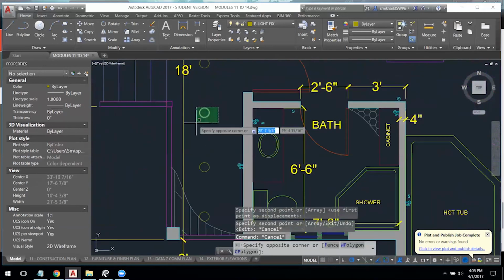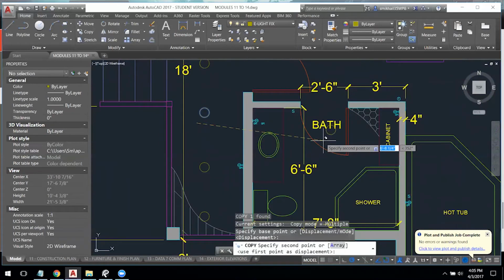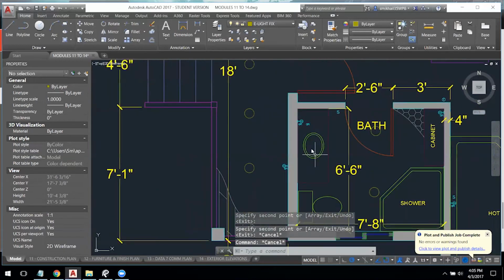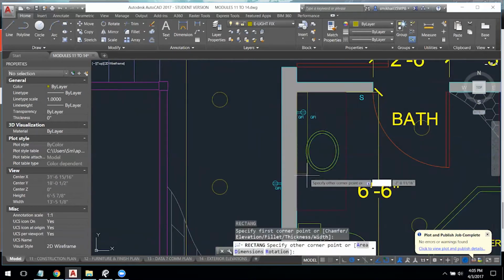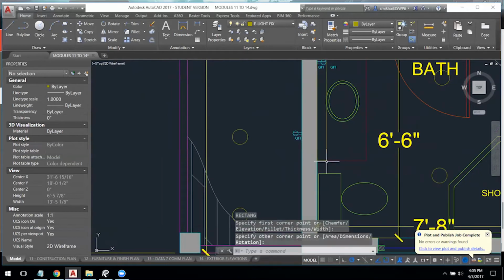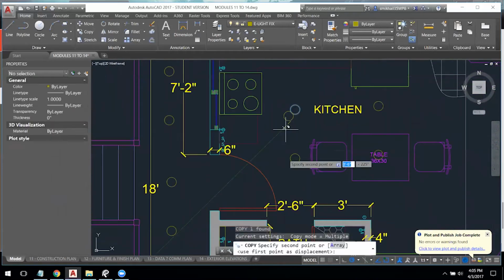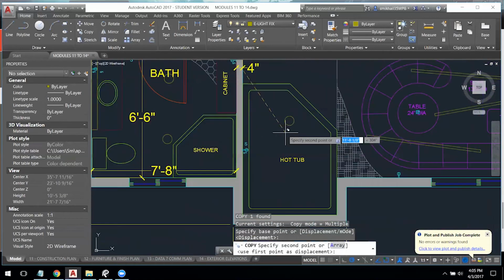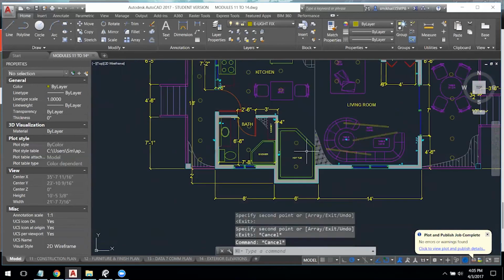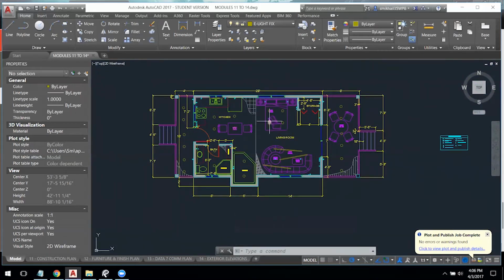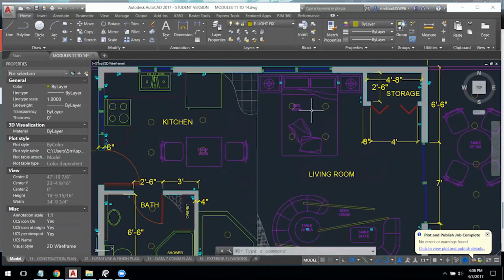Lastly but not least is the bathroom. We have two lights here, and we'll have another rectilinear light right by the sink area. And tub as well. So basically, when you're doing a lighting layout, you just want to take into consideration what is the function of the space below and align the light fixtures to optimize the amount of light being distributed based on the function.